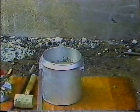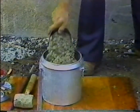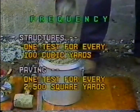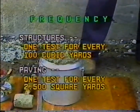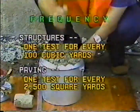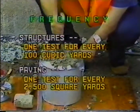Air content tests are just as important as the other tests and checks made to determine if the concrete is acceptable. As for the frequency of testing for structures, one test for every 100 cubic yards. For paving, one test for every 2,500 square yards. But any time that you suspect low or high air content, run another test. This program covers the pressure meter, an instrument that uses pressure to determine air content. I'll cover equipment, operation, and calibration. So let's get started.